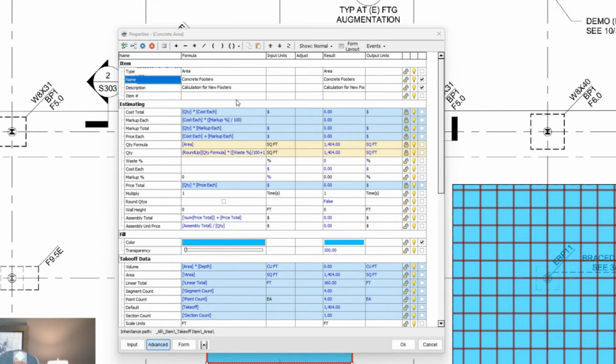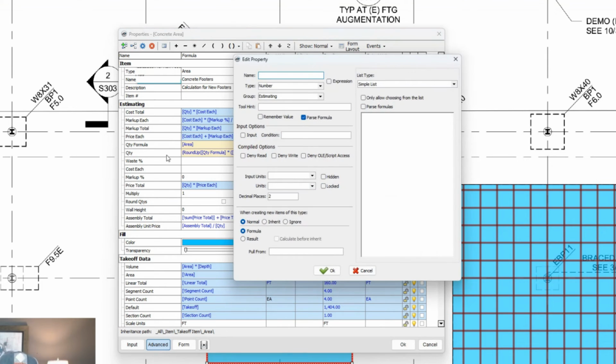all right. I brought up my cheat sheet over off screen here. One of the first things we want to do is we want this to be able to calculate volume. So we need to have a choice when we're selecting this template of what thickness. So we're going to go up here and, these are basically groups. So you need to click on the group you want to add a new field to. We're going to add a custom field and we're going to go up here. It says add property. And that's basically adding a new field. And it adds it to whatever group we're in. You see it says group estimate. We're in the wrong one. We could change it at this point.